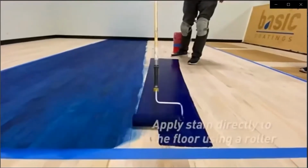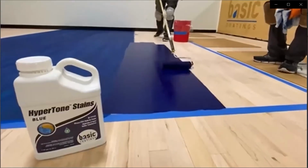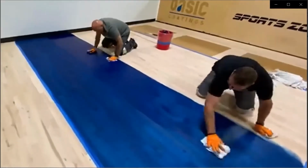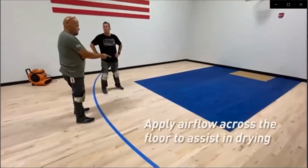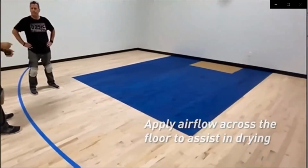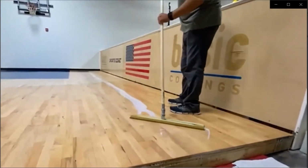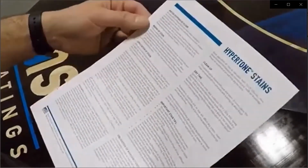Apply stain directly to the floor using a roller in 3 to 4 foot strips, working across the floor with the grain. Use thick terry cloth rags to remove excess stain and blend to a uniform appearance. Once application of stain is complete, wait 15 to 20 minutes. Then allow increased and balanced air movement and fresh air exchange to help dry the stain. Once the stain is dry, apply an appropriate Basic Coatings sealer and finish. Please refer to the Basic Coatings HyperTone Stain Technical Data Sheet and Hand Application video for complete information on this application method.